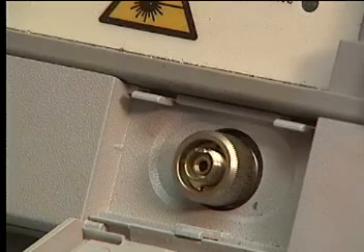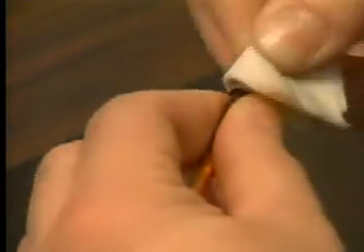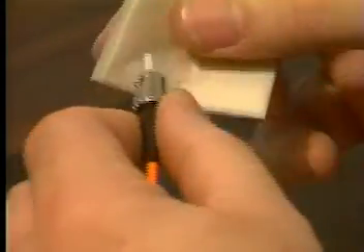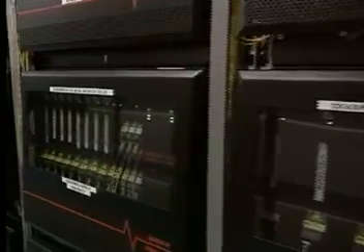Clean is a relative term, however. A ferrule end that is clean enough in one system may still be too dirty in another system. Today's systems using high-power lasers, extremely high bit rates, and multiple wavelengths now require strict attention to cleaning practices and the use of premium-grade cleaning products to maintain the quality of the connection surfaces.